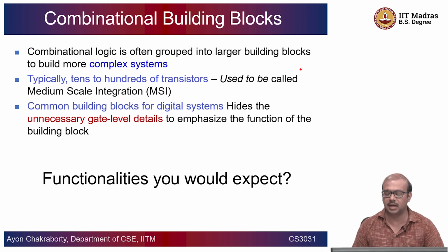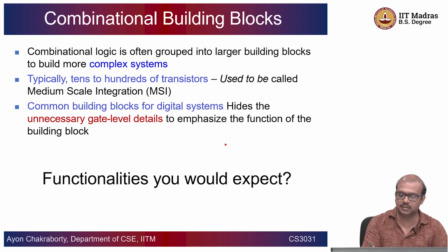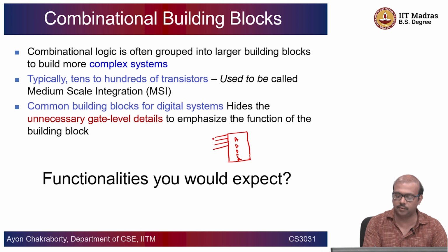Okay. So, I will go back to the adder example. An adder is a combinational logic block that adds two n-bit numbers, and that n could be 2 or 3 or 4 depending on what kind of adder you are considering. In this context, I can write this as a combinational logic black box. This is an adder, here we can write a 4-bit adder. There are 4 inputs of the first number that we want to add, and these are the next number that we want to add.